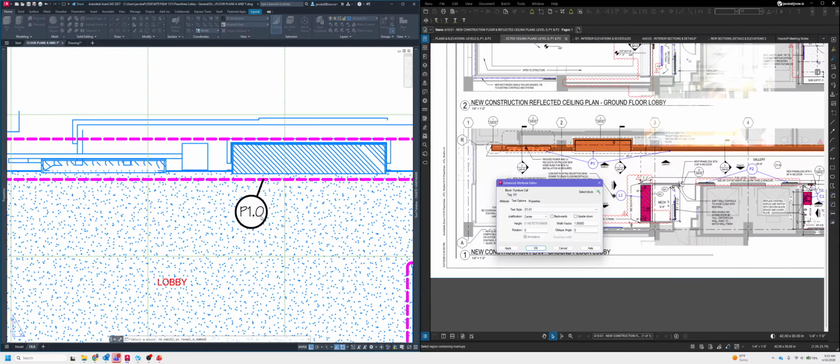And if you get into a case where you have text that doesn't fit within that bubble, like let's say this was actually P20.0, it doesn't fit, what you'd want to do is come over to your text options and shrink this down to something like 3/4 of what it should be.